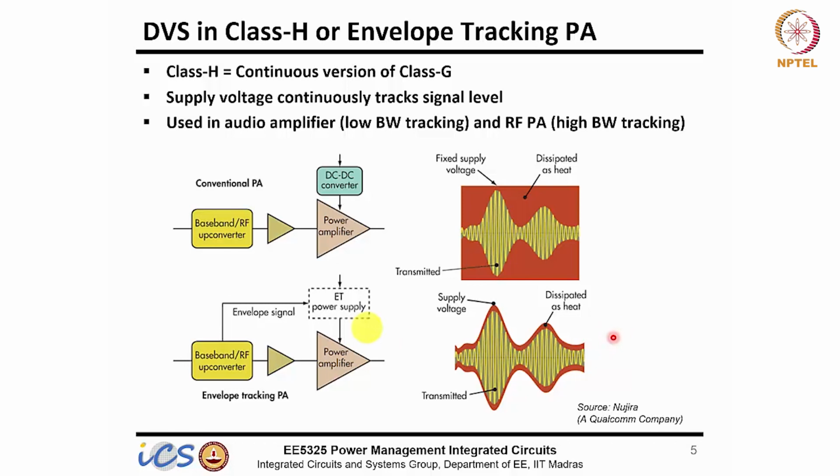Or in another way, you can think about it in terms of an LDO. If you keep the dropout voltage fixed, irrespective of your output voltage, then your losses will be fixed. You can always achieve a high efficiency no matter what the voltage is. But if you keep the input supply fixed, at a lower output voltage the dropout will increase and your efficiency will drop.